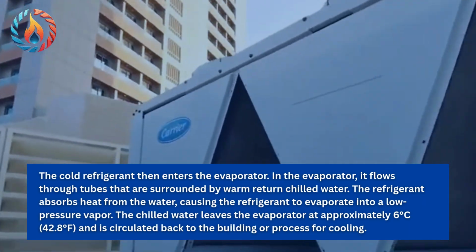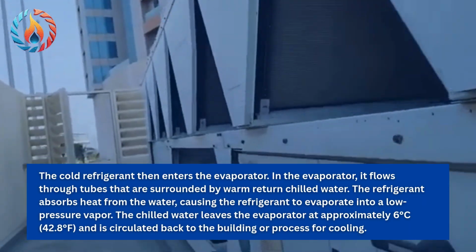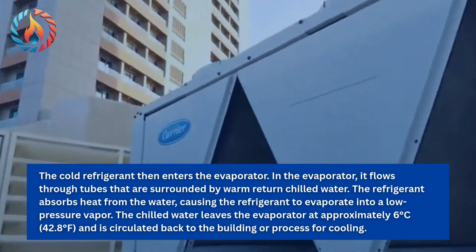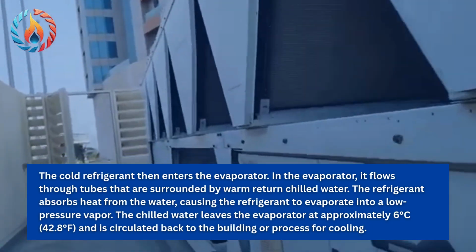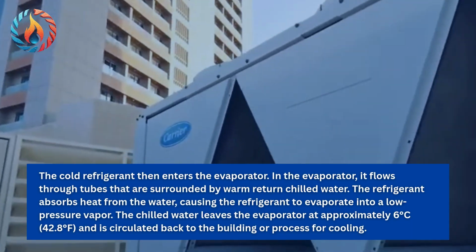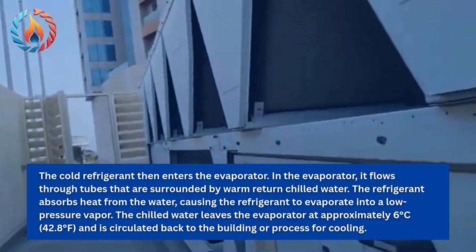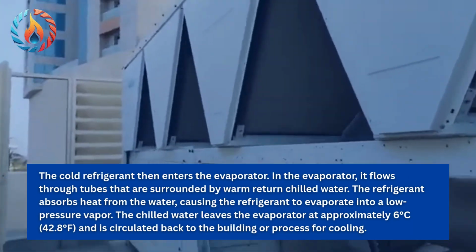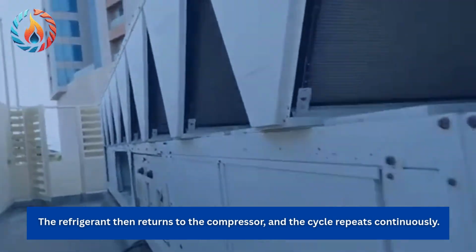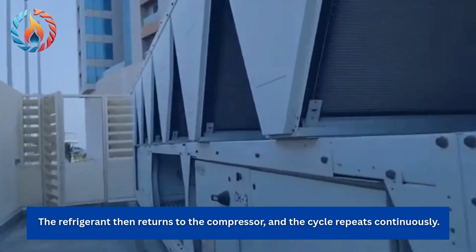The refrigerant absorbs heat from the water, causing the refrigerant to evaporate into a low-pressure vapor. The chilled water leaves the evaporator at approximately 6 degrees Celsius, 42.8 degrees Fahrenheit, and is circulated back to the building or process for cooling. The refrigerant then returns to the compressor, and the cycle repeats continuously.